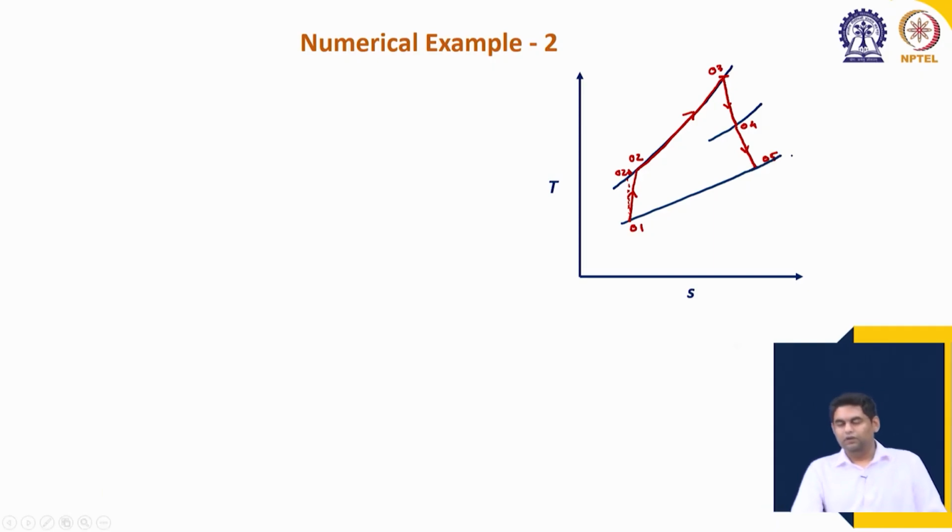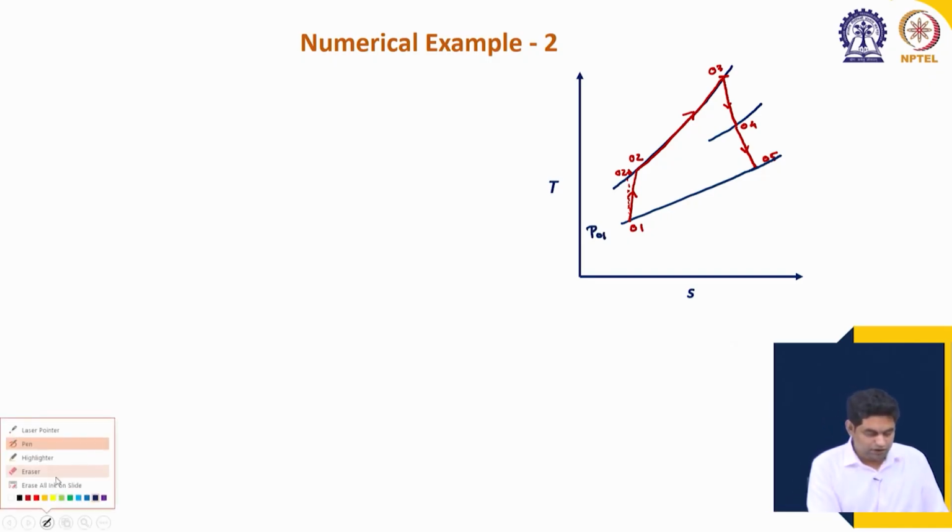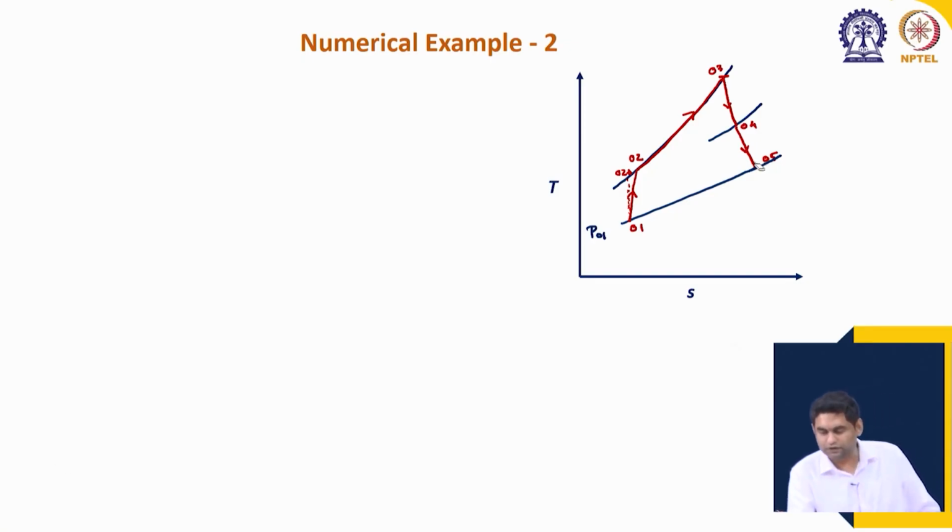Okay. So, now the cycle can be closed by going from 05 to 01 using a heat exchange process. So, the important pressure values here are the inlet pressure P01, because there are no pressure losses. Okay. So, there I have made a mistake again. Here it is given that the exit pressure from the turbine is higher than the atmospheric pressure.